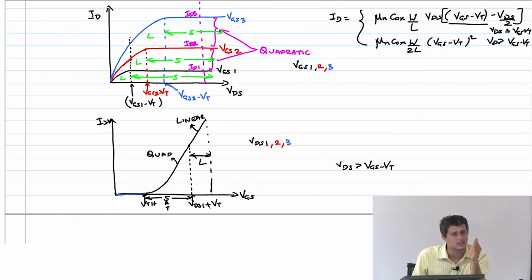Now VDS is higher, VGS has just gone beyond VTH. The current will be greater or lesser than VDS1? So you are basically saying that because it starts in saturation, the current will basically be the same till that quadratic region, right? Okay, interesting. So then, yeah, that seems logical.